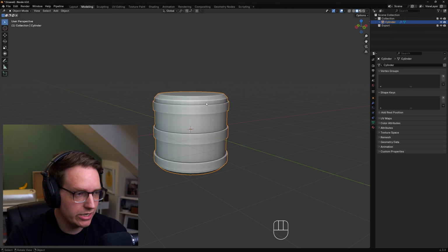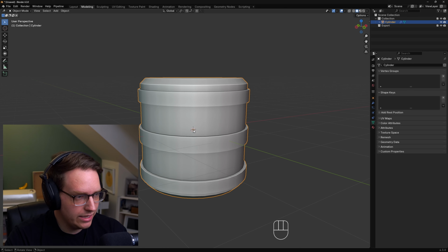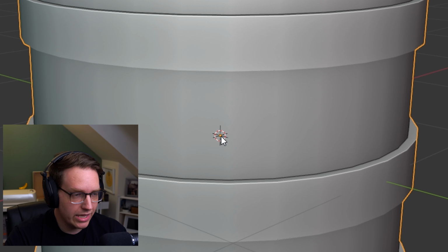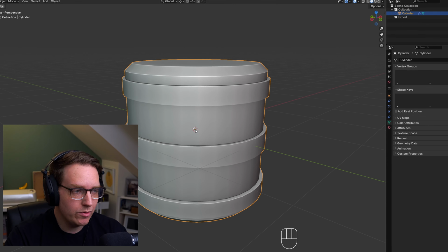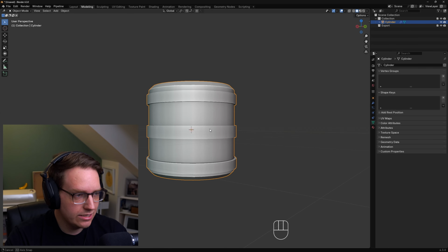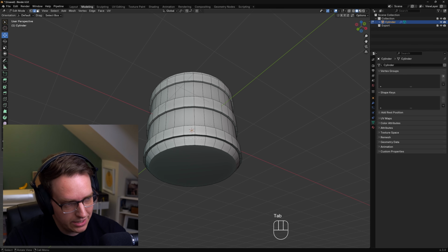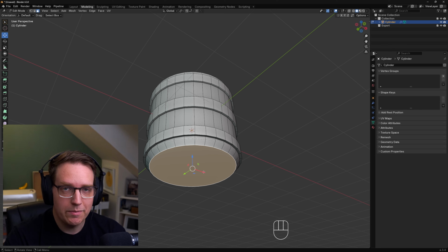We want our object sitting up higher, and that little yellow dot that's almost impossible to see in the center of our mesh right now is our pivot point. And we want to assign that to a different location of our mesh than the very center. So what I'm going to do is set the pivot point first. So I'm going to go back into edit mode, select my mesh, hit Tab, hit 3 for face mode, select the bottom of my mesh. I want my object to sit on the base, and I want it to pivot around the base of the object.